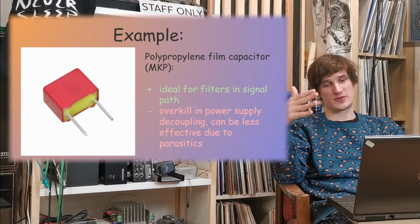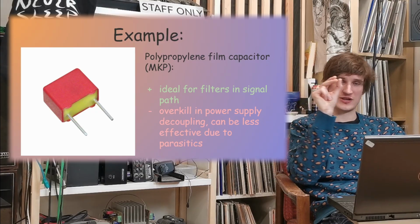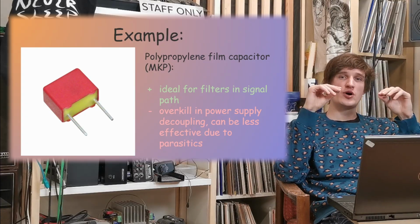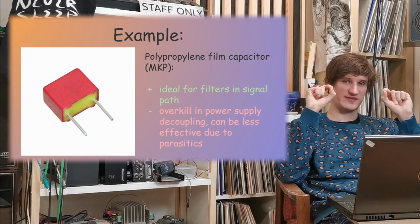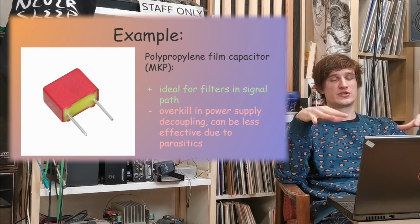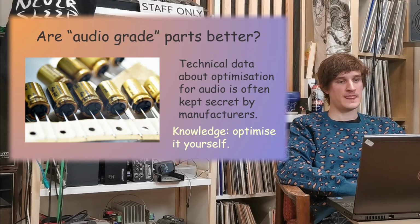And when speaking about power supply decoupling, when speaking about putting capacitors of small values very close to the device that draws some current, you want to keep the leads very short, and you don't want to have any parasitics. So here this polypropylene film capacitor could hypothetically ruin the performance when dealing with a decoupling application.